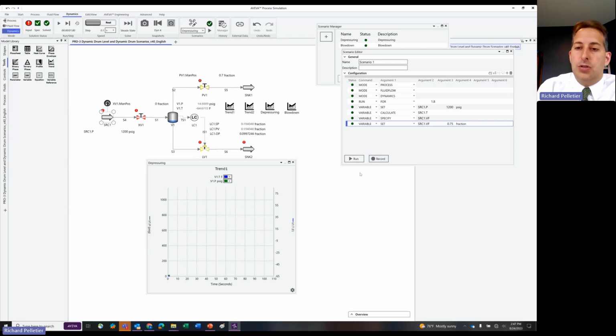And then what you can do is you can come back and you can edit this. Maybe I didn't want it to run for 1.8 seconds. In reality, I wanted it to run for a minute. So I can just edit this. Maybe 1200 wasn't the exact value I needed. I needed 1500. So I can change everything that's in this table, but getting it set up, the infrastructure essentially, is easier to do by recording and then making the changes that I want to make and then just stopping the recording. If I want to put things in manually, I can click